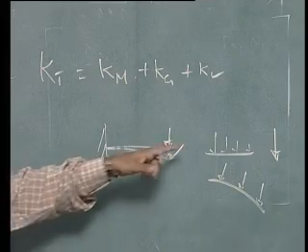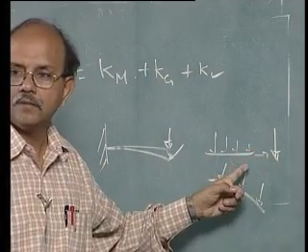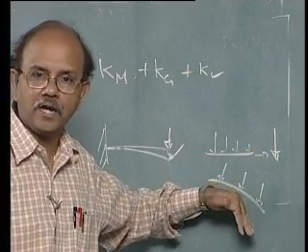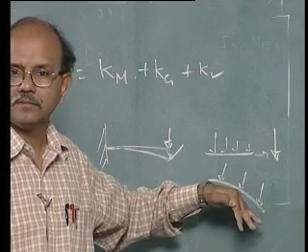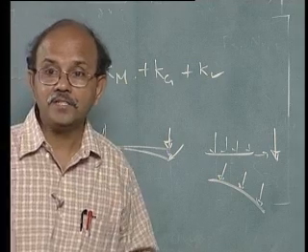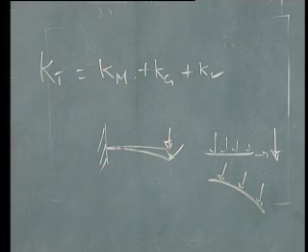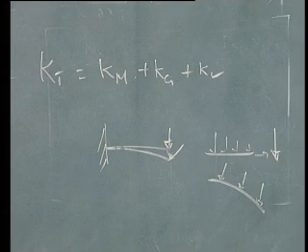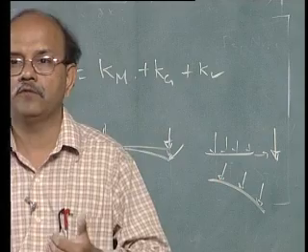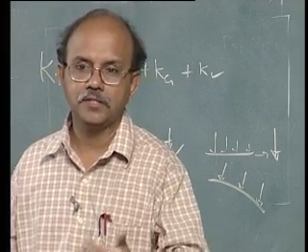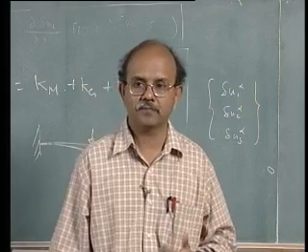In other words, there was no horizontal component to this when it was like this. But when the deformations are large, there may be a horizontal component to it, and so on. So in other words, the load follows the deformation. Which means that F varies with U. So that is the contribution for the stiffness matrix, and that is what we call follower forces.